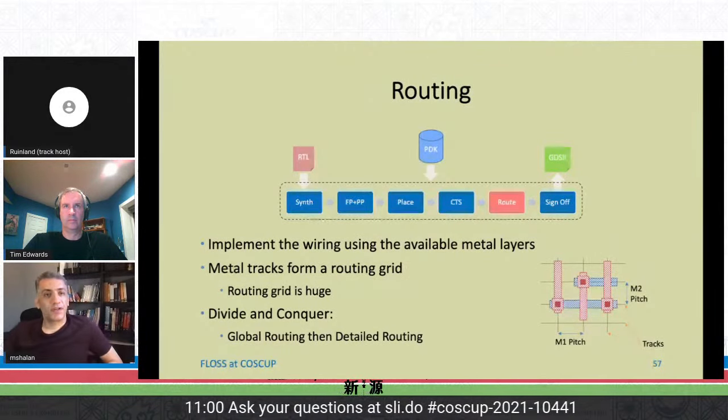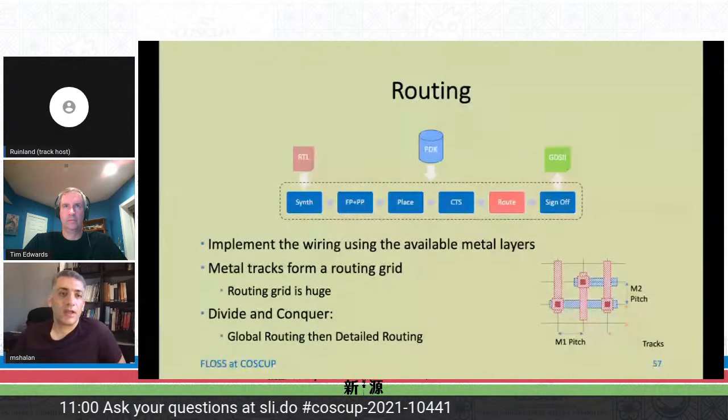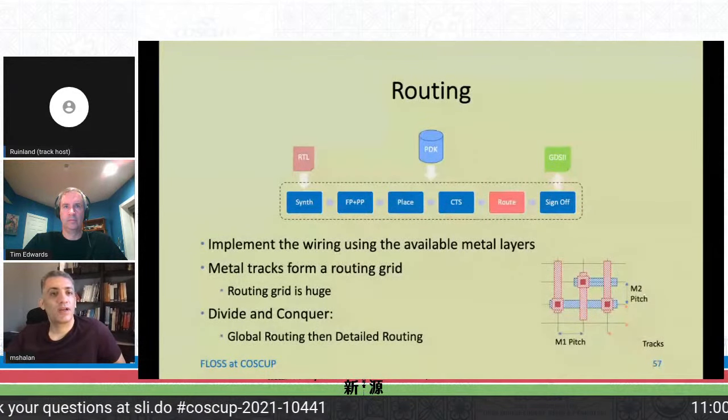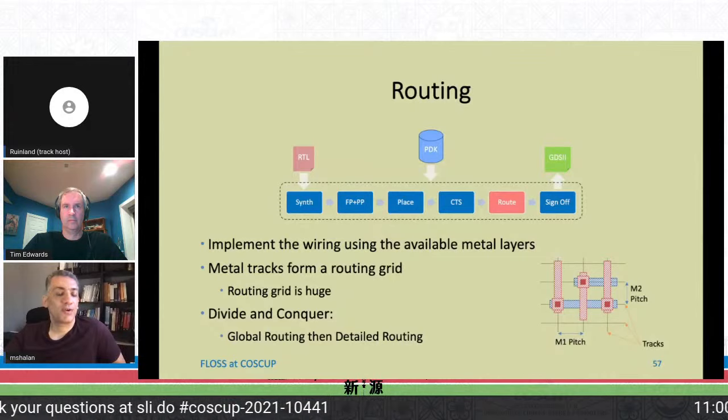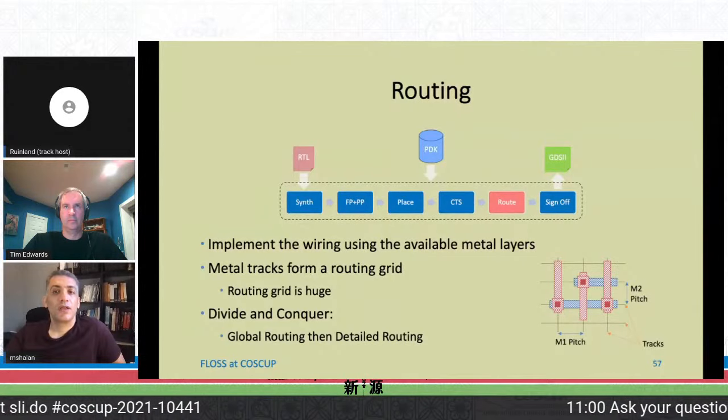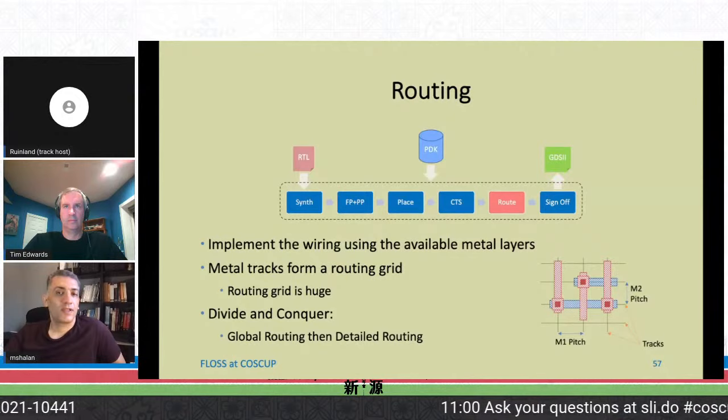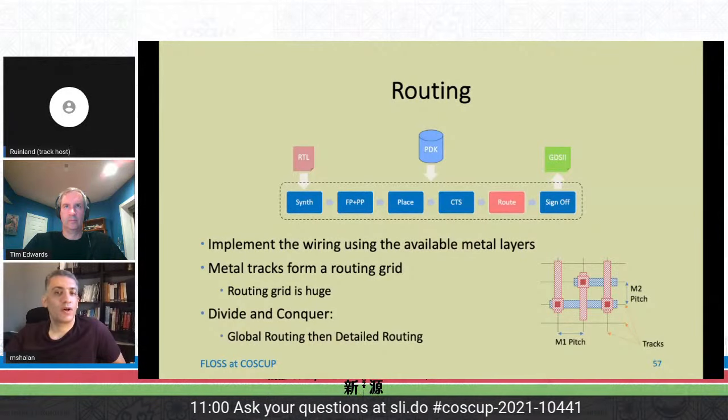After clock tree synthesis comes the routing. Eventually, after the placement of the cells, we have a fixed number of routing layers based on the fabrication process. For example, in the SKY130 process, we have 6 routing layers. These 6 routing layers are named LI, which stands for local interconnect, followed by 5 metal layers, metal 1 up to metal 5.